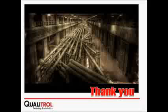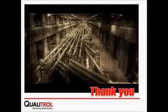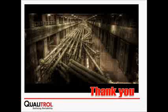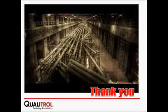Okay, Thomas, correct me if I'm wrong, but it has to be energized or it has to go through the high voltage test set. You need to have voltage energy in order to detect the PD. You need to have an electrical field to induce those particles in order to detect. So I hope that answers the question, because the PD pattern really would be visible under high voltage stress. So you need to have a high voltage test lab to simulate that. So it can't be just your normal portable unit you can use to apply some currents and voltages.